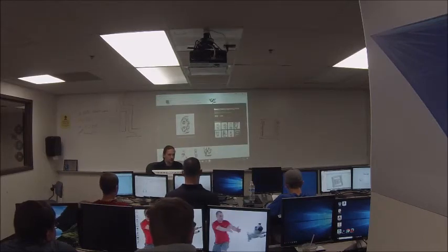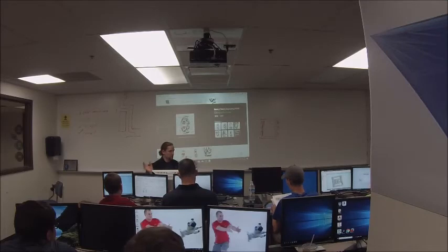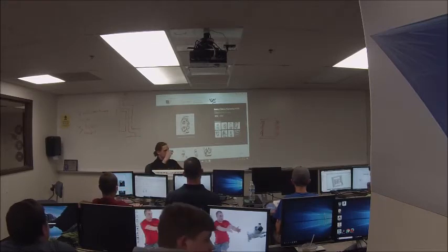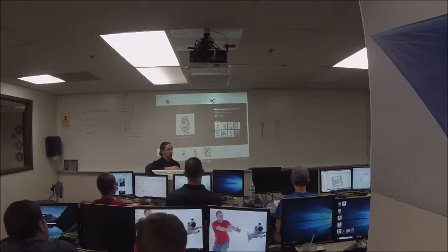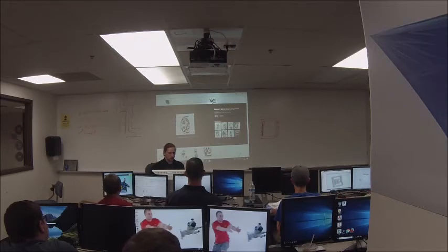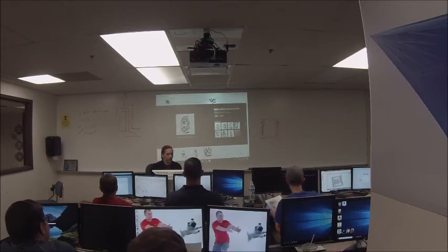It has an outer race, which is this outer part, and it has a round groove cut on the inside of the outer race. These are precision ground, they're very, very precise. It has an inner race, and there's a round groove ground on the outside of the inner race. The inner race is put inside the outer race, and bearing balls are put around the outside that roll in between the two surfaces and provide support. And then they're held in place with what's called a ball cage, which is this kind of stamped metal piece that holds the balls very, very loosely, but keeps them from falling out, and keeps them evenly spaced so the loads distribute.